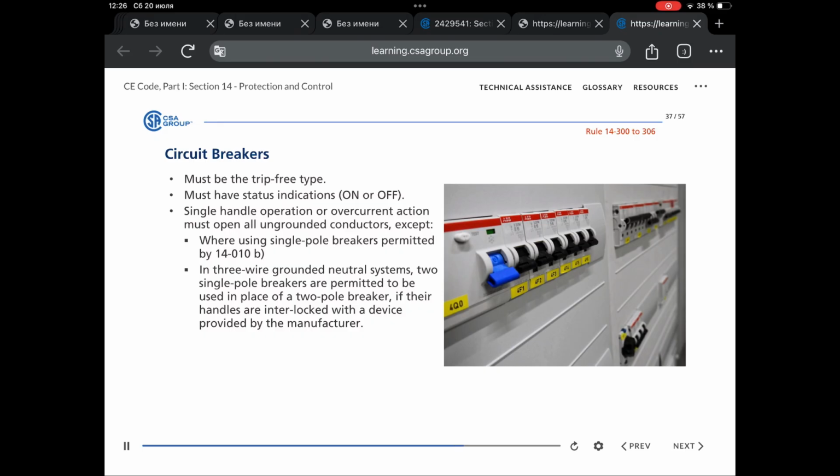Most breakers have a fixed calibration that is factory sealed. However, larger circuit breakers may have adjustable settings. As a result, circuit breakers must be designed in a way that making adjustments to the settings is difficult. It may require a specific tool or breaking a seal. Table 25 provides the requirements for the number and location of tripping elements based on the type of system being used.